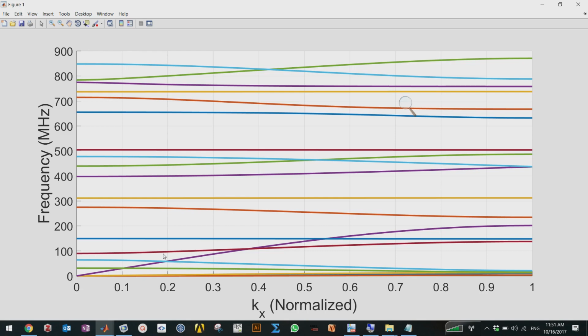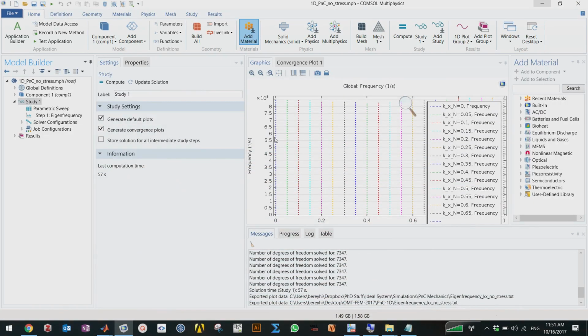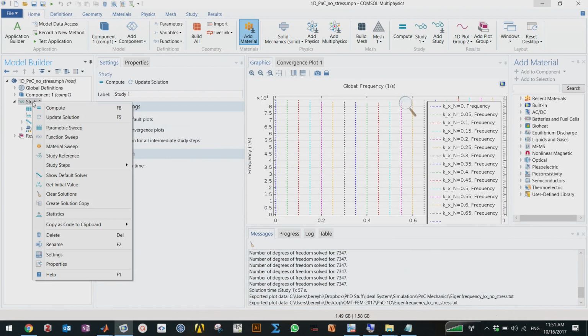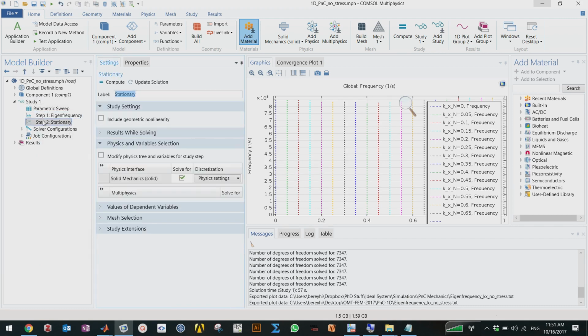So here I need to have some boundary conditions for this study that I added. So what I do here, I come to solid mechanics, and in the linear elastic material, you can add an initial stress and strain. So here we can add the initial stress. Amir already explained it to you. So here for my stress matrix, I'll write, for example, stress initial for X, initial for Y, and for Z you already know that it relaxes in this direction. You don't need to, because it's not bounded in Z direction.